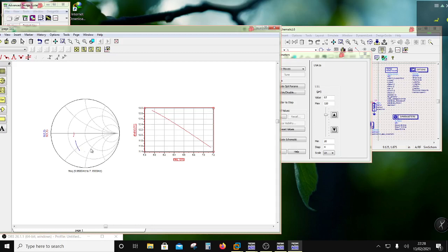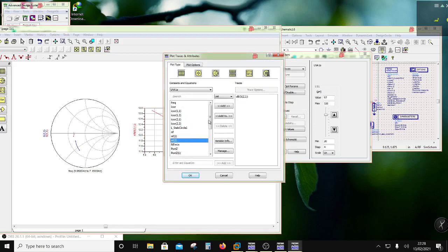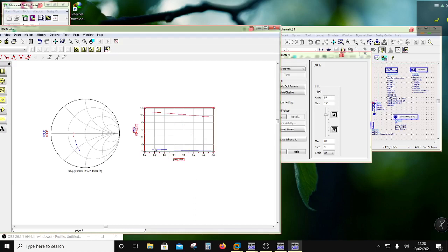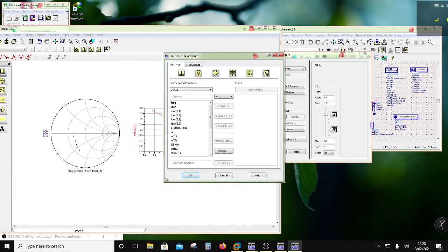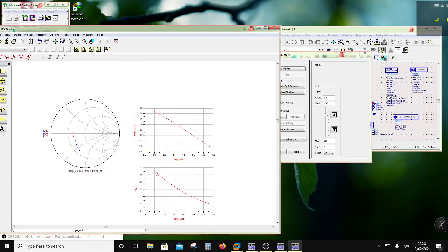So also I would look at the noise figure, for example, NF2. Okay, so the NF2, rather I'll put it on a different curve so that I can see it properly. So I'll put NF2 here. So it's of order 2 point something, right? Now let's see, how do I get over here? I can use a series capacitor and a shunt inductor, right? And on the output side, I am not allowed to use anything other than one more capacitor, right?